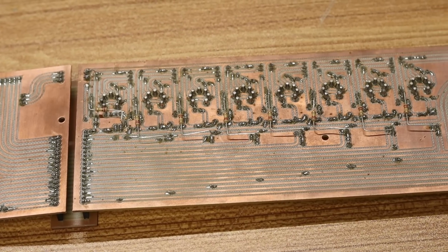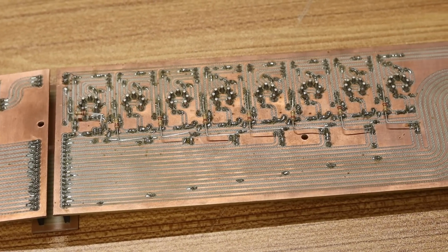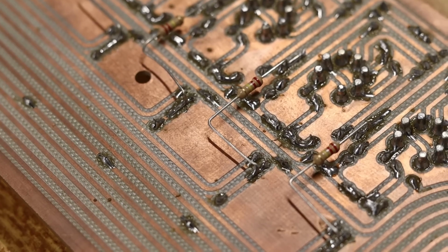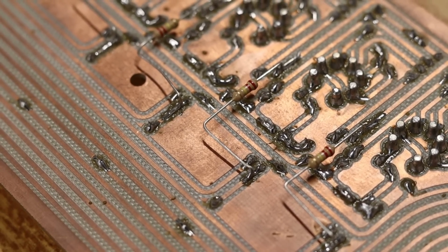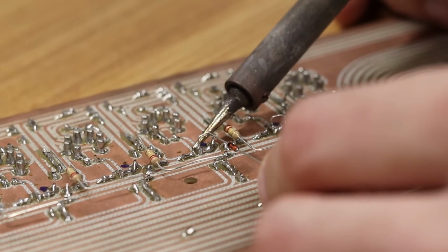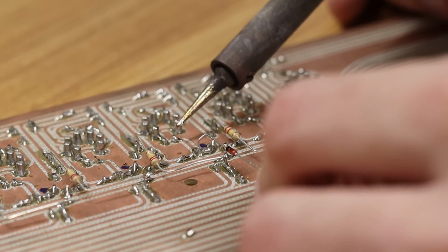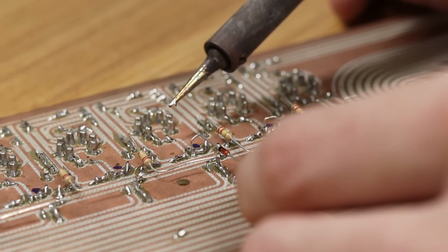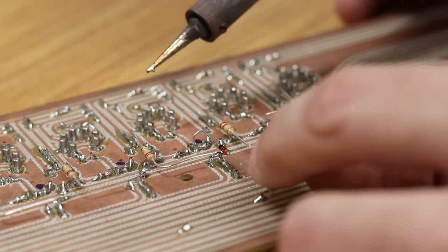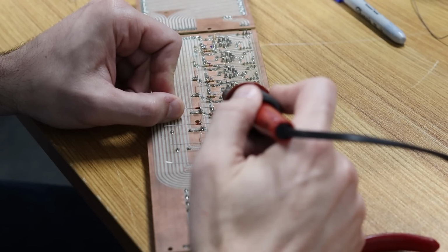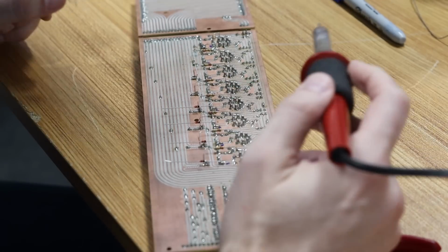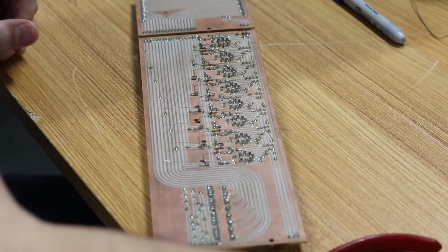And this is not the first time I've bodged this board. I was having some signal integrity issues, so I added some extra pull downs, and while it cleared up the integrity issues, that actually is completely unrelated to the problem that we're diagnosing now. I'll bend up some new diodes and get them soldered into place. I'm going to need to connect 7 new diodes to the NOR gate input sections, all the while being careful not to route them in a way that'll cause a short.